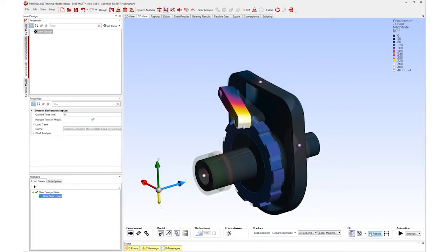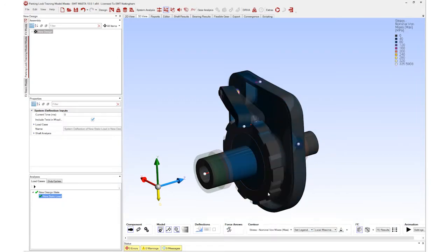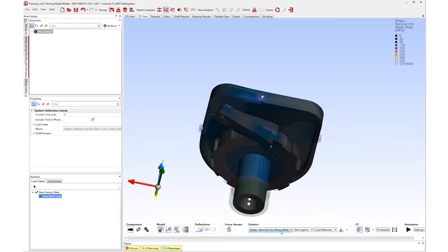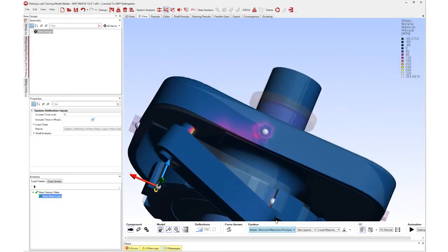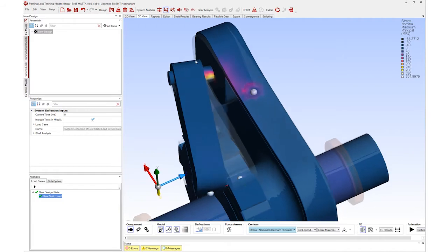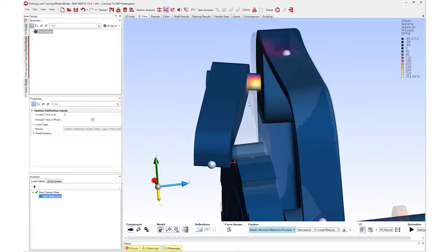It's worth keeping in mind that the mesh you would normally use for stiffness matrices such as these probably isn't fine enough for an accurate stress calculation, but it will at least give you an impression of what's going on. Okay, so I can see where the stresses are occurring in that particular model.